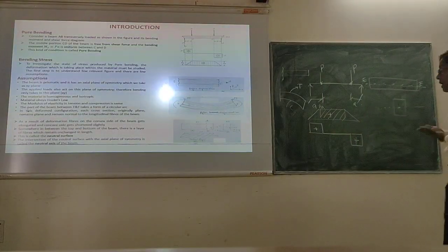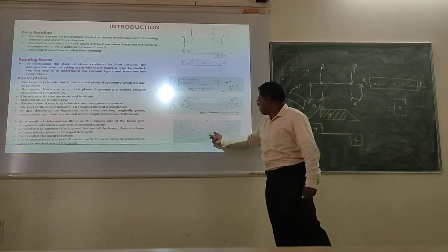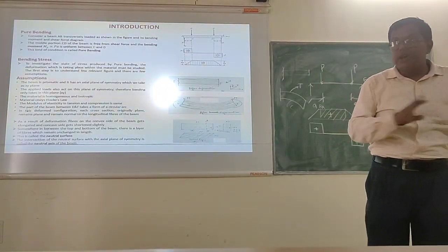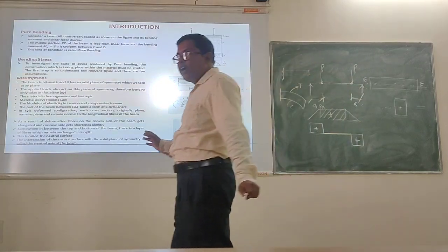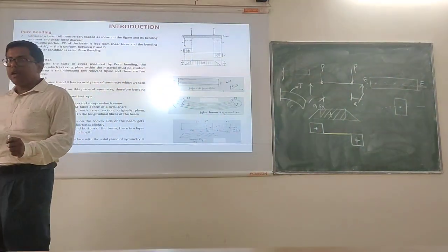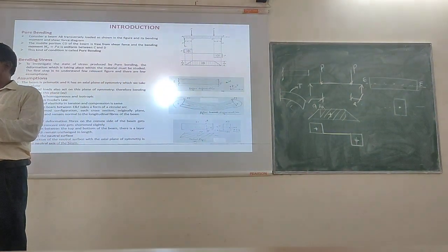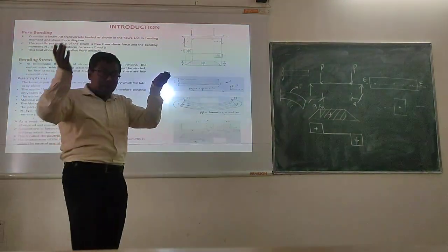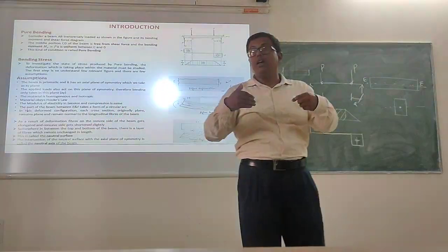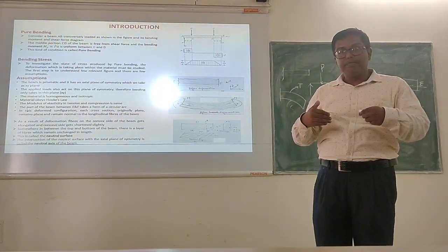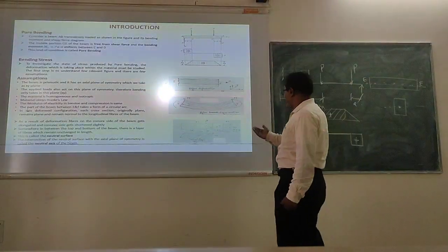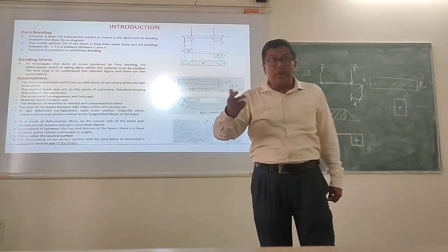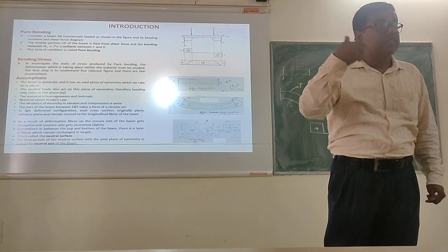And that surface will be termed the neutral surface. So there is no extension, no elongation, no shortening. So that surface remains neutral because of the loading condition coming from the external loads. Clear? So that neutral surface will come into the picture when we understand our bending stress theory.